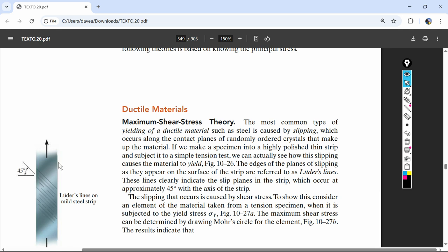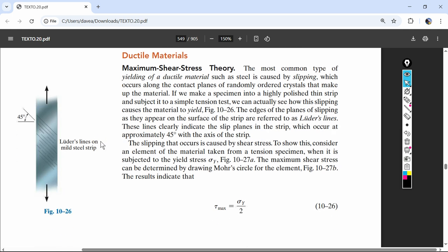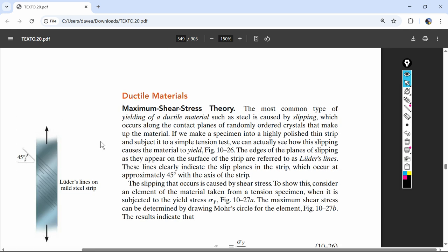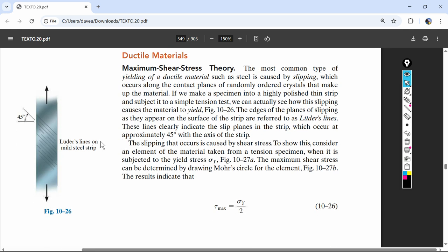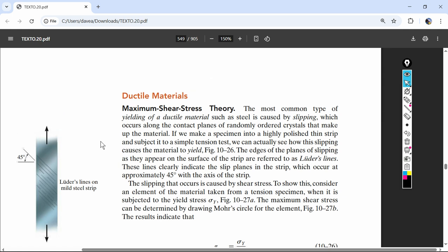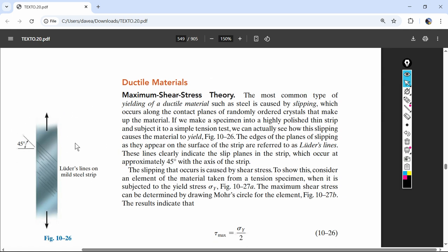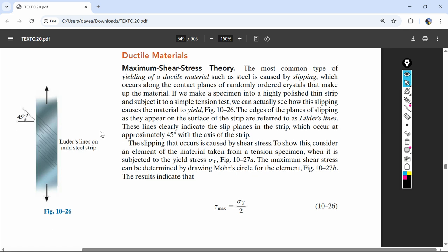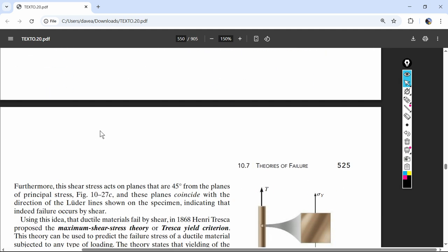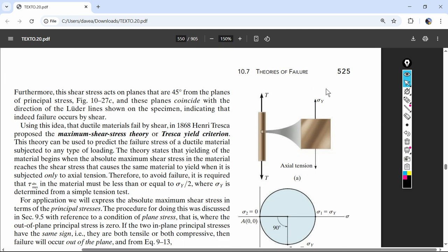But this is yield. That y is due to what we were just talking about the entire time. We're dealing with ductile materials. Their failure occurs at yielding, and failure with air quotes. Obviously, some things can yield and still maintain their strength as long as they're kind of redundant, but yielding is what we're going to cause failure. If you get past the yield state, you overloaded it. And so this is sigma yield.